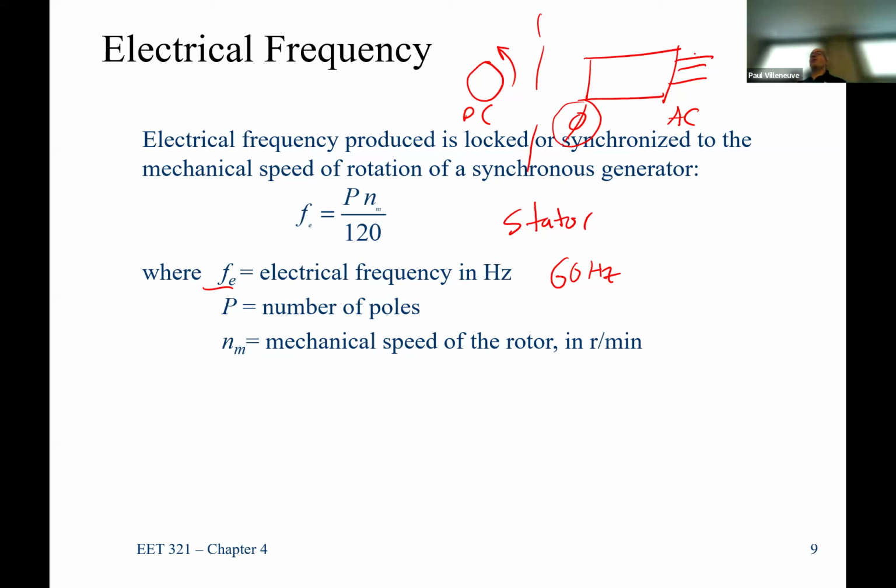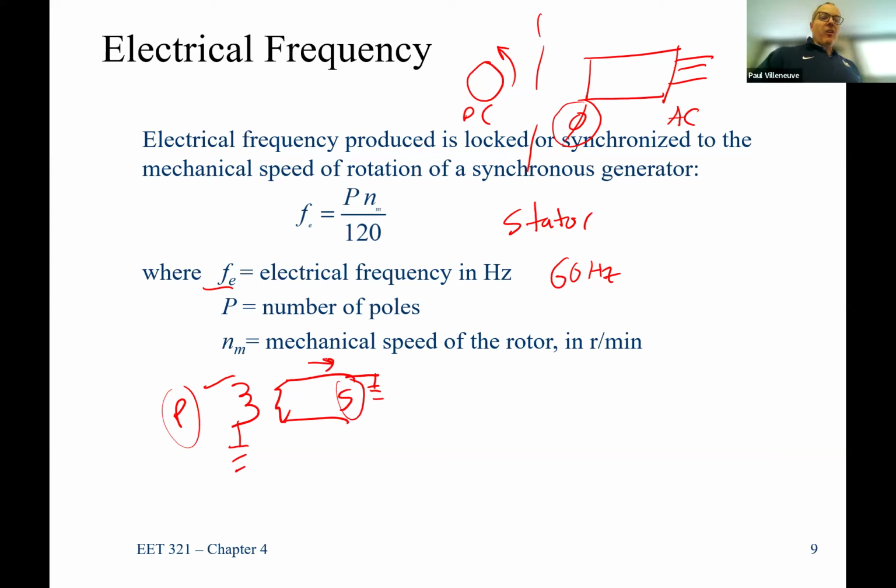So what you're going to start to see now are two separate circuits, kind of like in a transformer, right? Here's the primary winding, here's the secondary winding. Are those having any influence on each other? If I've got a ground over here and I put a ground over here, does anything happen? They're electrically isolated from each other, aren't they? So the analysis for this part can be done somewhat independently of this part, except we know that the current over here is related to the current over here. That's not the case over here. The current that goes into the DC circuit is somewhat independent, or 100% independent, from the AC.